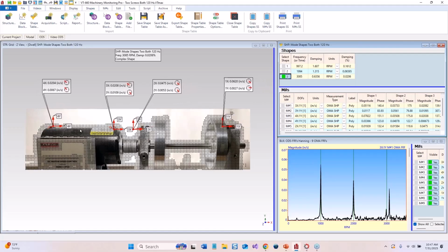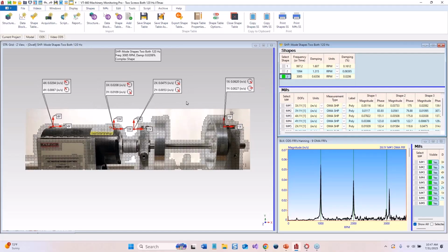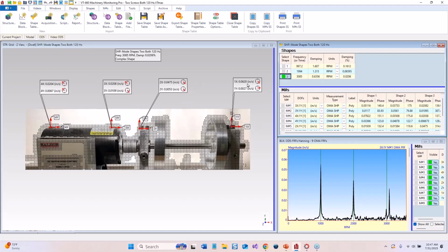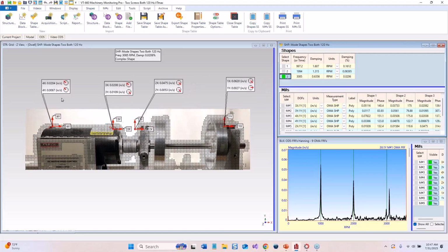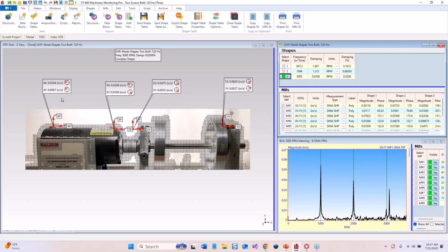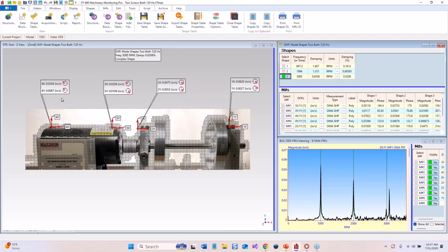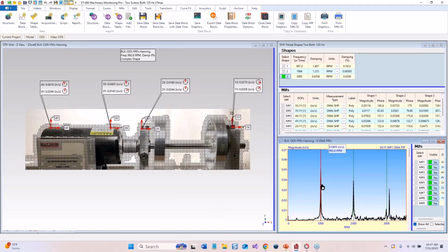Clearly out of phase. The motor and the bearing blocks, the points are just moving back and forth, but they're 180 degrees out of phase. We can see that with the little phase diagrams here, and we can see the inches per second. All this data has been scaled to velocity, and you can see at this frequency, that's not the overall motion, but the motion at the resonance.